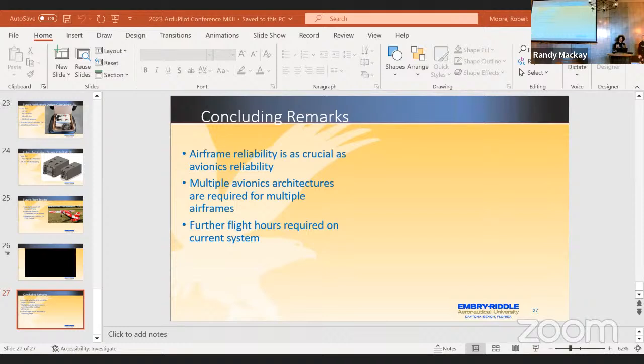The point I was making there is, the state is starting to talk about passing around actual internal navigation decision-making, in which case a single autopilot can no longer make a decision. Essentially, you've got three pilots in the cockpit. That's right, whereas the system that I envisaged with the standby mode, all of that is being done internally by one autopilot, and then the others are kept up to date with that in case they get switched to. So it's not guaranteed on any single plane.